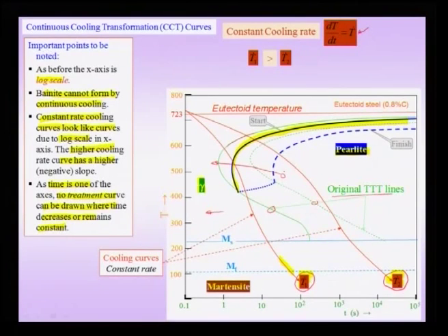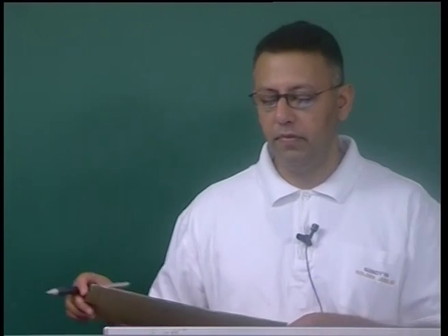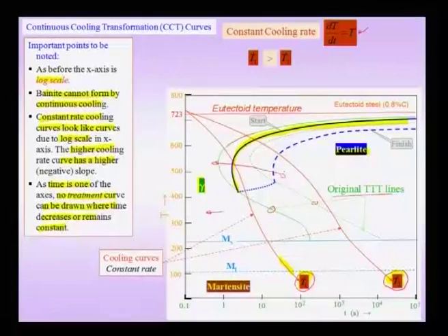because in such a case my starting point is in the pearlitic phase field, and for drawing all TTT diagrams for eutectoid steel, we have noted that we are interested in the eutectoid transformation. That means that my starting phase has to be the gamma phase, which is my austenite, and I study the transformation of this gamma into various alpha plus Fe3C or the martensite, which are the two possible microconstituents or phases or the microstructures obtained after this transformation.